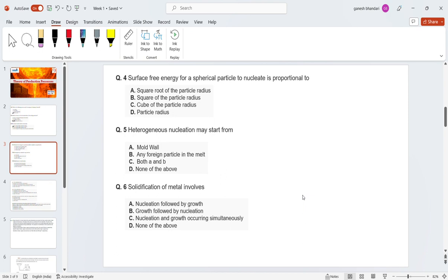So the tendency of that particular soldering alloy will be to form a ball type of element, a soldering ball with tin and lead majorly in it. That's why in soldering some particular waxes or other things are added to enhance its wettability. Because as the wettability increases, the surface tension gets reduced. Same from the correlation of the Young-Dupré equation I'm talking about.